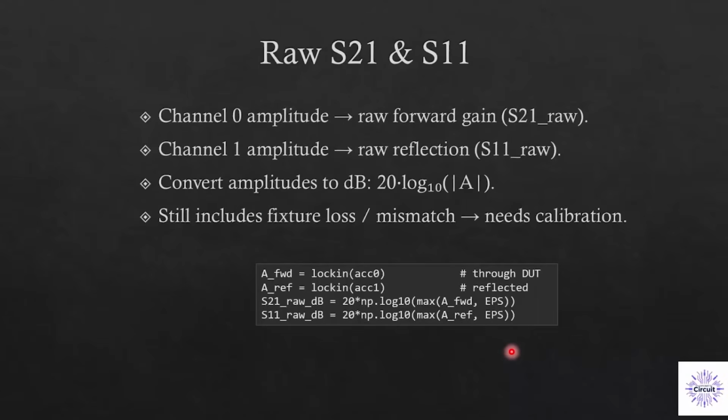So now that we can measure the amplitude at our receiver port, what we are going to do is connect our TX to the input of the device. Then the output of the device is connected to my first RX port, and the output of the RF bridge is connected to another RX port of my ADALM Pluto.